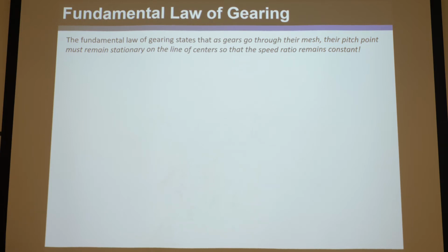And as long as they're conjugate, as the teeth are going through their mesh, their pitch point remains the same, and that means their ratios don't change, and so the angular velocity ratio maintains constant, independent of the angular position of the input or the output, and consequently, you obey the fundamental law of gearing.